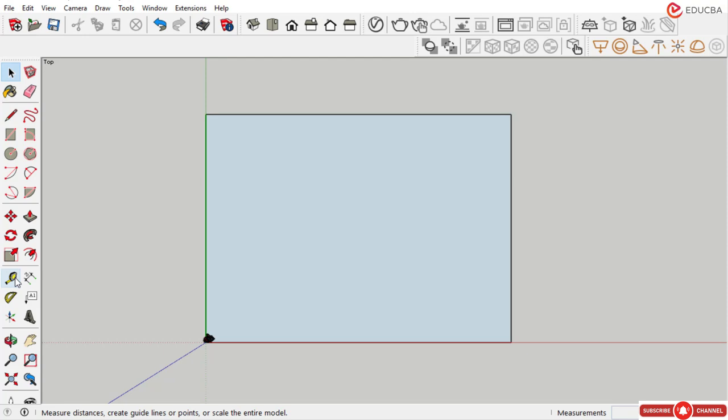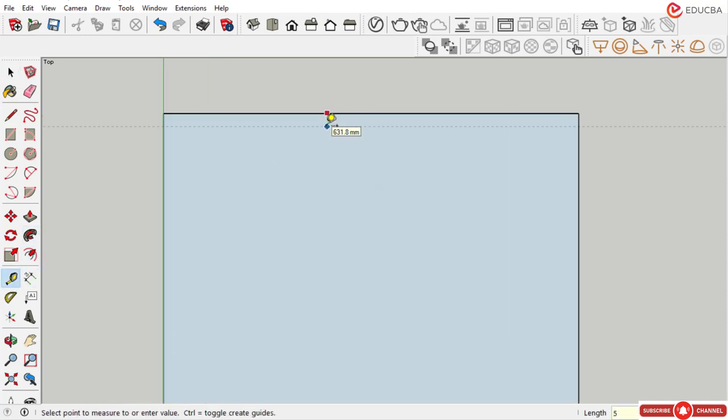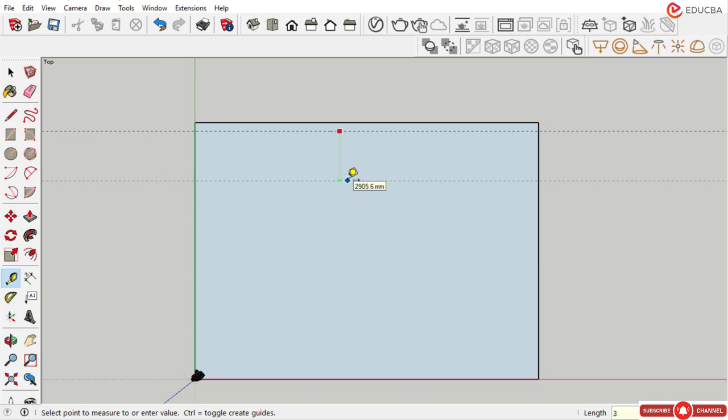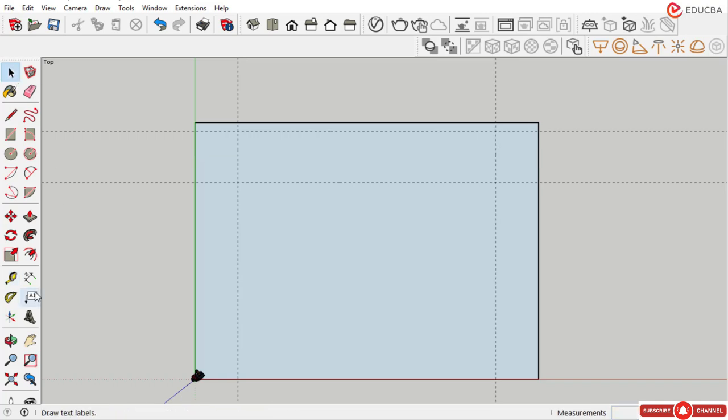So here I will design first the cabins and the VIP sitting area, VIP cabin and VIP sitting area into this available area. So let's start from here to here, make 500 like this, and from here the width of the cabin or the depth of the cabin is around 3 meter. So here I will design 3 meter. Then from here make 3 meter or 2.5 meter, and from here 2.5 meter. So if I measure this area from here to here, it is 15 meter. So in this 15 meter we have to design the VIP cabin as well as VIP sitting.